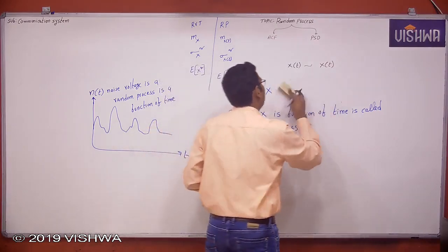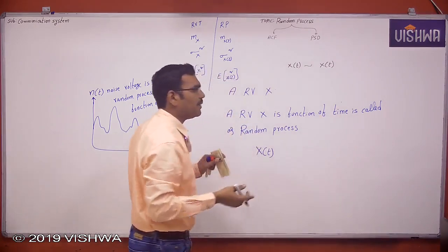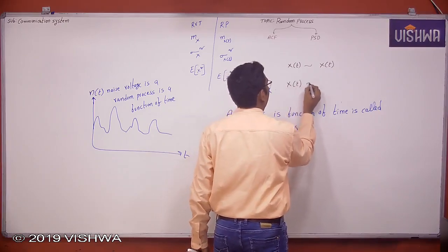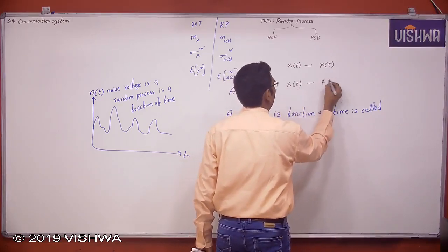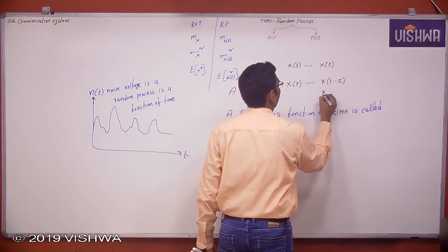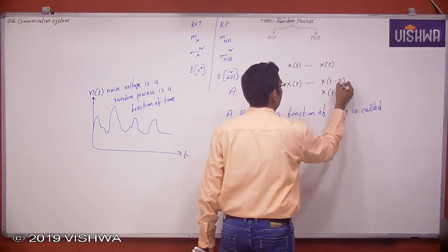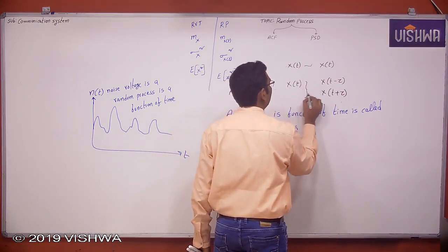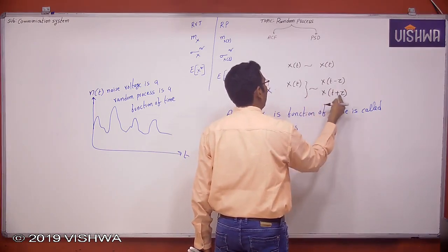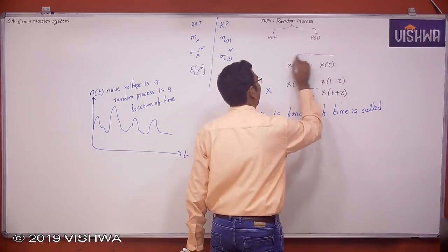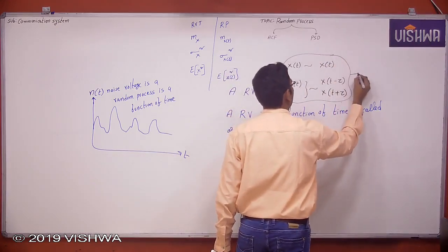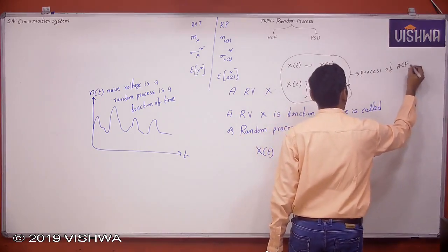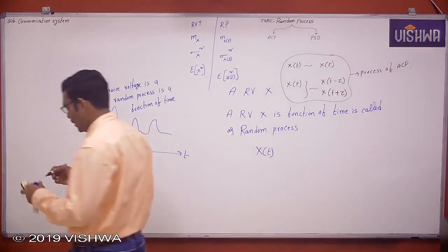Now a signal compared with the same signal. Sir, how can I compare, because both are the same? You can compare like this. Take a signal and compare it with a delayed version or an advanced version of the same signal, with some variable tau, and find any similarities. That is the process of autocorrelation, the autocorrelation function. Understand or not? Okay, now that we will see.